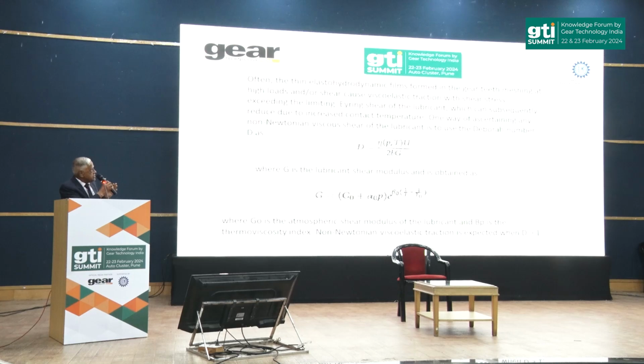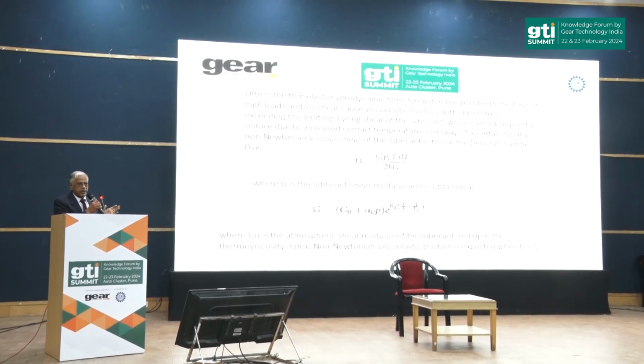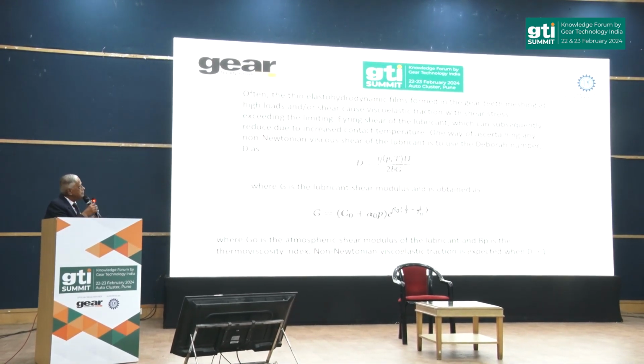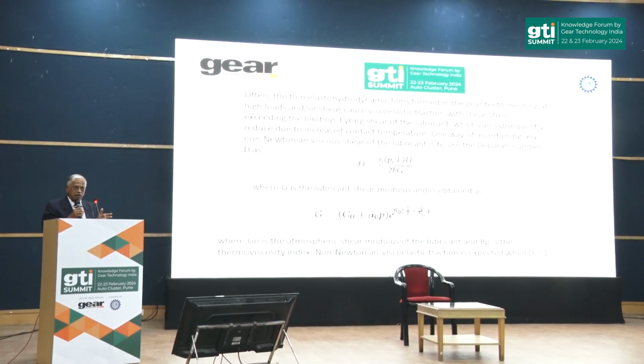So when EHD is taking place between the two meshing teeth under load, when the pressure increases, it causes certain viscoelastic traction as the shear stress occurring on the oil film is exceeded by the applied load. So the applied load starts working against the film. Naturally, there is a point at which it shears, and thereafter the behavior of shear stress to shear strain becomes non-linear, which they say is non-Newtonian behavior.